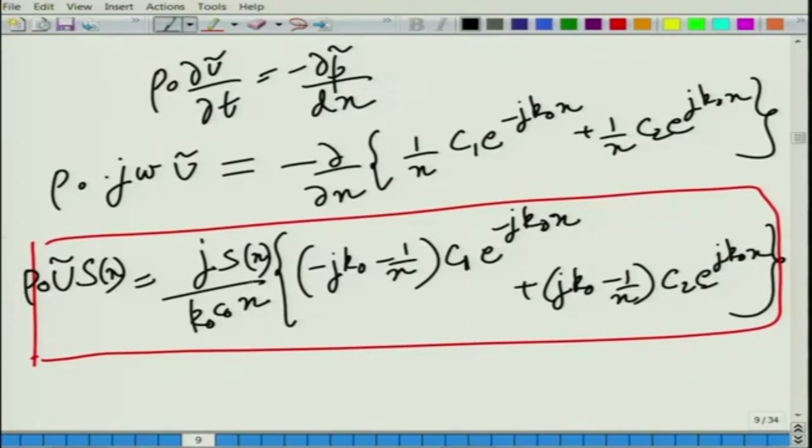So, now what do we need to do for a conical duct is that we need to fix our axial coordinates, that is where we are heading. So, here at x1 and x2 like I have been talking about. Once we decide what our x1 or x2 value or the length L is, and obviously the radius at both the points, then we can formulate the transfer matrix.